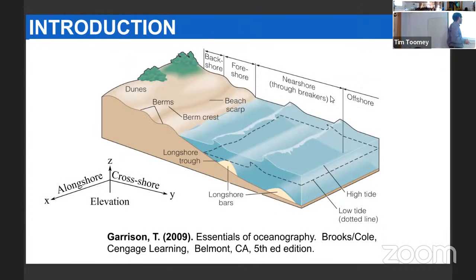First of all, let me talk a bit about beaches. You know that they are very dynamic systems. They suffer the effect of marine forcing: waves, currents, turbulence, interaction between waves and currents, and wind. And since the beach bed is not fixed but made of unconsolidated sediment, it responds to this forcing and changes the shape of the bed. So there's a feedback and coupling between the morphodynamics, the bed shape, and the hydrodynamic forcing.